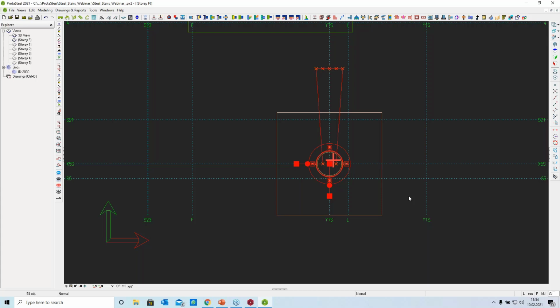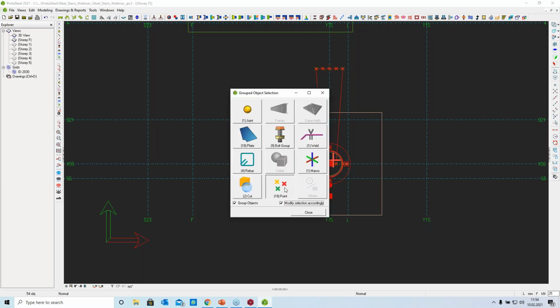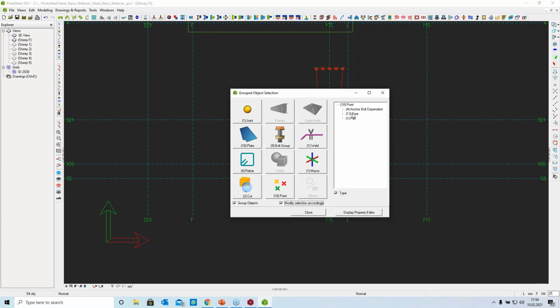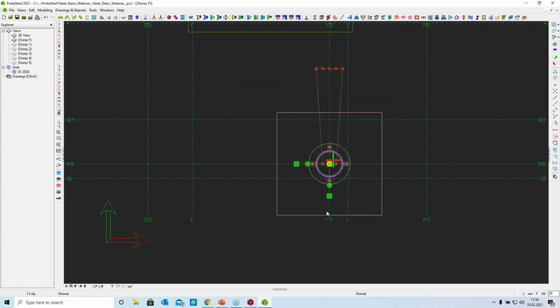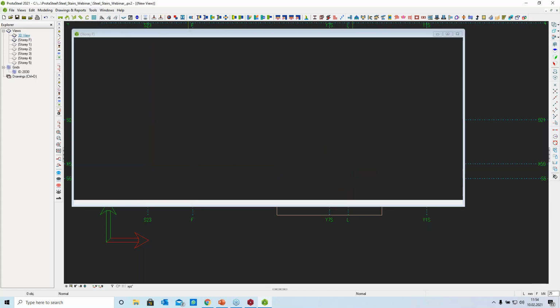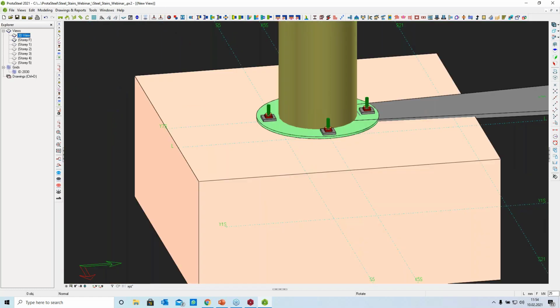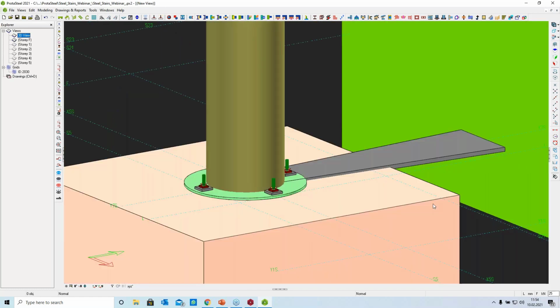So we can press the enter button, select points. For example, we have 13 free points here. So I have selected them and we can delete them by the delete button on our keyboard. Okay, let's go to the 3D view and we can specify the position with the Ctrl W button on our keyboard. So you can also obtain these shortcuts from our knowledge base. You can check the knowledge base for these shortcuts also.